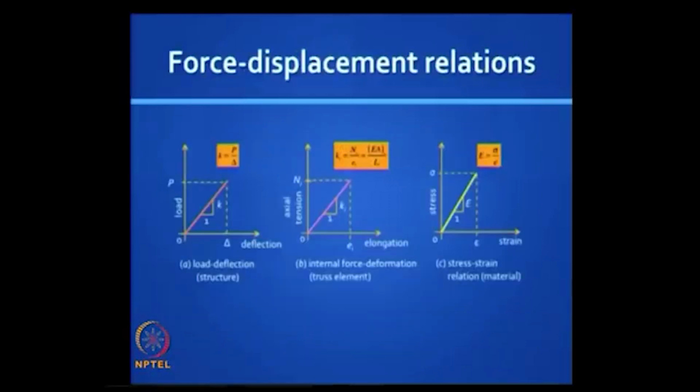elastic behavior. And if you look carefully, force displacement relationships, P by delta is, if you reduce the element to a spring, to an elastic spring, you use the word spring stiffness, right? That's called axial stiffness in this case, and you will find that P by delta is the same as N by E, for the simple reason that N is equal to P and E is equal to delta for a single element. So if you have different bars, you can define axial stiffness Ki for the ith bar as, you can prove it to be EA by L, okay, from the definition.